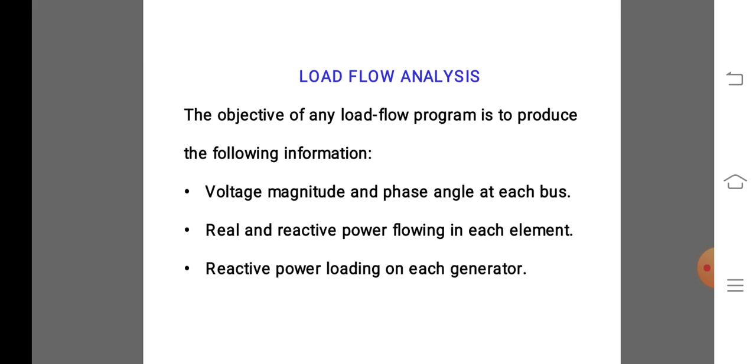Load frequency control always senses the busbar frequency and power frequency. Then the difference is fed to the integrator and to the speed changer, so the line frequency is always maintained constant.